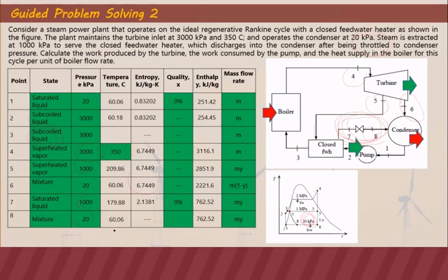And for the temperature, we can use this pressure and enthalpy to get that. Since this is in the saturation region, it's just the same as point 1. So 1, 8, and 6 have the same pressure. And 7 and 5 also have the same pressure, that's 1000. But the temperatures of 7 and 5 are different, as you can see.